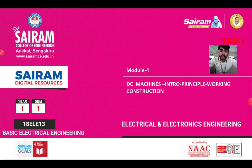Next, where do we use these DC machines, DC motors or DC generators? We have different types of DC motors like shunt, series and compound motors. The shunt motor is for constant load application. The series motor is for heavy load, high speed application. Variable speed is possible with both, but for constant speed application, that is the shunt motor.